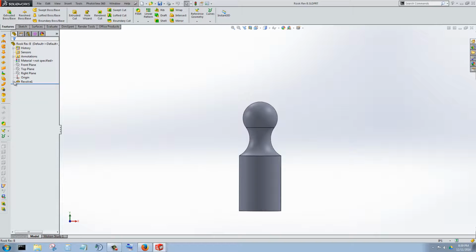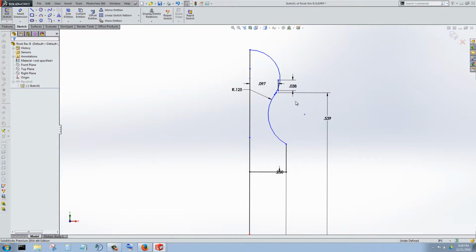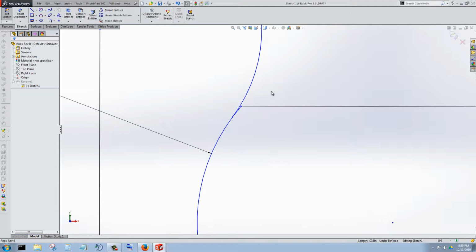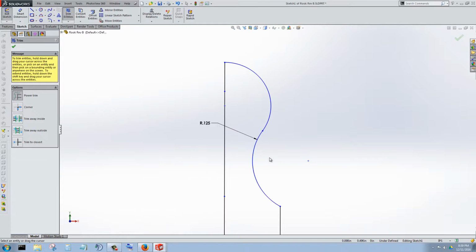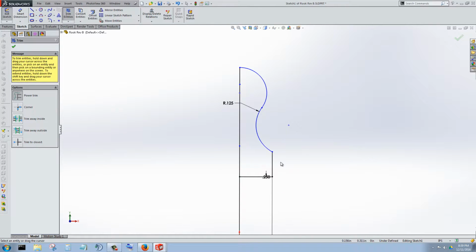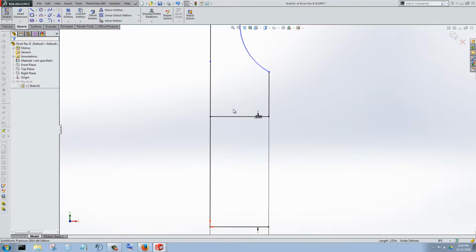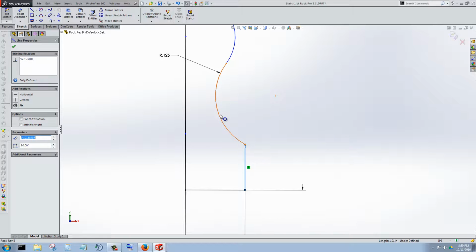Now with the Rook, I do want it to be slightly taller. So perhaps, what's this? That doesn't need to be there at all. And what's that? Trim that off. Didn't notice that geometry. What needs to be a little bit taller is, whoops, undo that. Just trying to drag that dimension out of the way. Okay. What needs to be a little taller is this line right here.